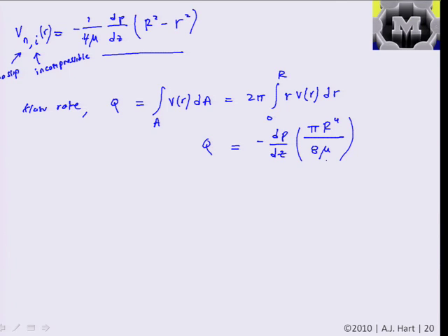And the pressure gradient is negative because pressure drops as the flow goes down, so we have a positive flow rate. And as the pressure gradient gets bigger, we can drive more flow through the pipe. As the radius gets bigger, we can drive more flow through to the power of 4. So that's really indicative that the flow resistance, or the amount of flow we can pipe through, is strongly dependent on the radius. And as the radius gets smaller, with a very, very strong dependence, you require more force to counteract the friction at the wall.